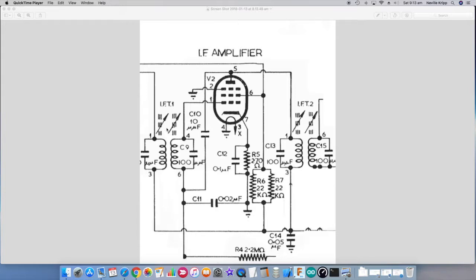So in effect, you will have a lower overall Q factor. However, it'll give you a wider bandwidth, so higher fidelity signals will be able to be transferred through that transformer.